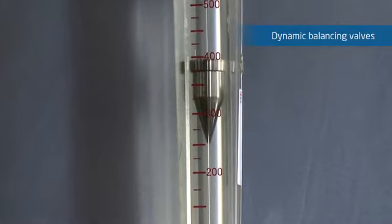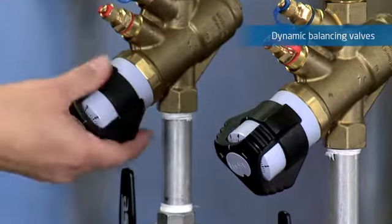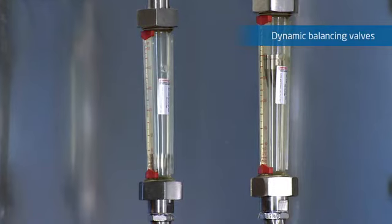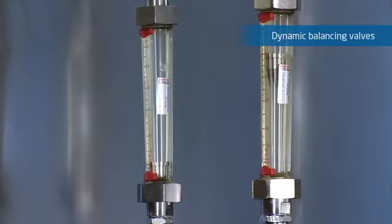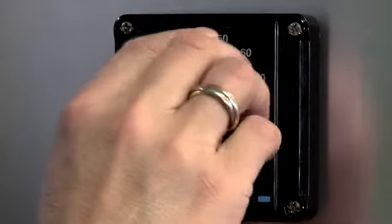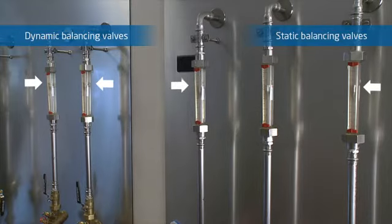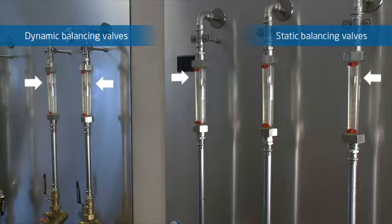In contrast to the static balancing valve process, when a temperature control valve changes position, the flow in other parts of the system is not affected. Even when the pump pressure changes, the dynamic balancing valves continue to maintain the set flow, whereas the flow in static balancing valves will fluctuate.